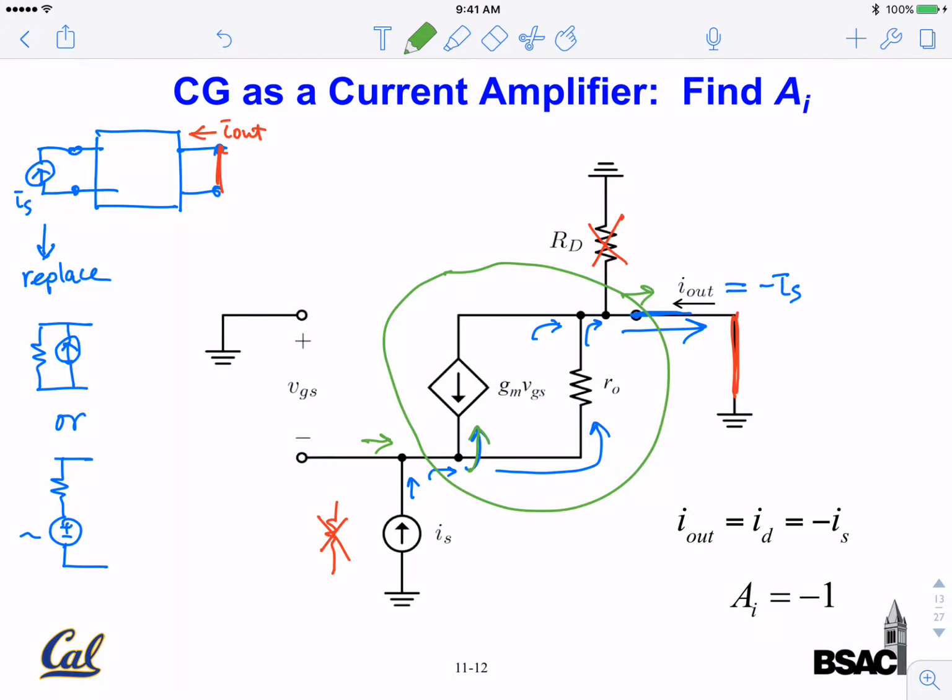Okay, so even if we don't use this generalized view, let's erase the box and just look at the more traditional picture. All the current flowing here has to go into either path 1 or path 2, and path 1 and path 2 will recombine at the second node. So you apply KCL twice. You don't have to solve the individual component. You still get the same equation.